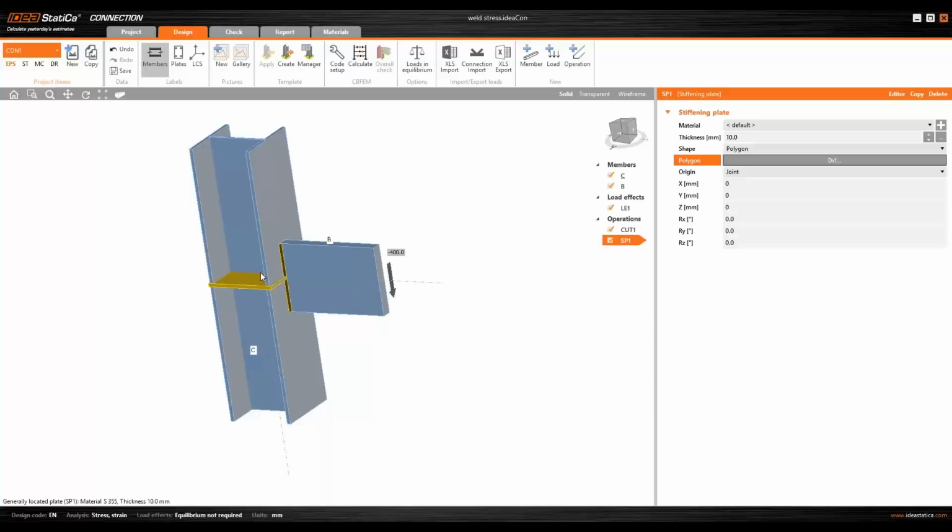So if your drawing is in millimeters, you have to switch in the import window. What Adam showed, you have to switch to millimeters, and if you are in meters, you have to be in the same. Yes, units. We cover this transformation during the import, so you can do that. Okay. Yeah, and of course, I want maybe just to mention that you can also import not only plates, but also different openings, different shapes of openings. It's also possible.